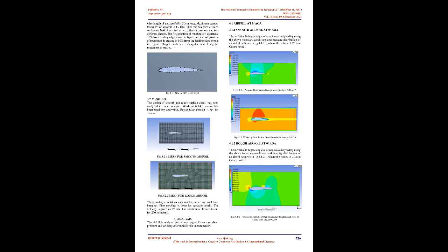The NACA 4-digit wing sections define the profile by: first digit describing maximum camber as percentage of the chord; second digit describing the distance of maximum camber from the airfoil leading edge in tens of percent of the chord; last two digits describing maximum thickness of the airfoil as percent of the chord. The NACA 2412 airfoil has a maximum camber of 2% located 40%, 0.4 chords, from the leading edge with a maximum thickness of 12% of the chord.